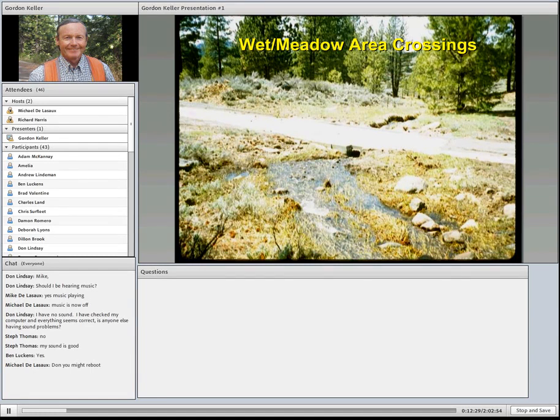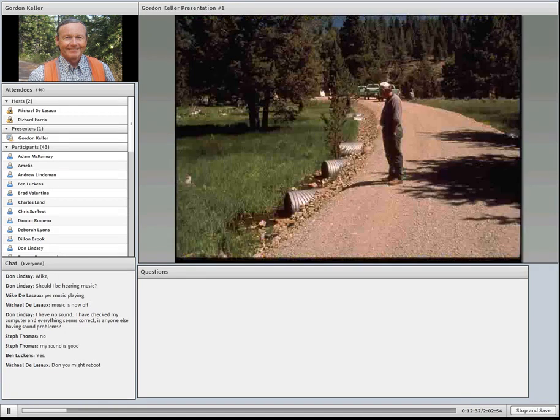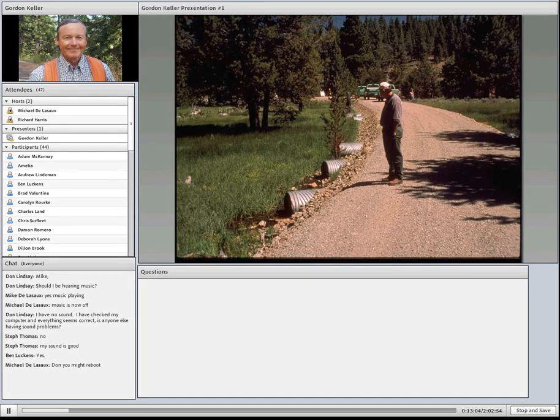So today, if we're crossing an area like this, where we really shouldn't be, the approach is ideally to put in enough drainage to keep the water table high, to keep the water where it naturally belongs. But what this takes is something like a permeable rock fill or a battery of culverts to keep the flow dispersed where it's always belonged. And so it's a fairly expensive treatment, but I look at it as making up for being in a bad place, a bad location in the first place. But sometimes we're there. A great deal of this type of work has been done in the Southwest and here in Northern California, trying to fix roads that have been damaging meadows and drying up meadows over the years.